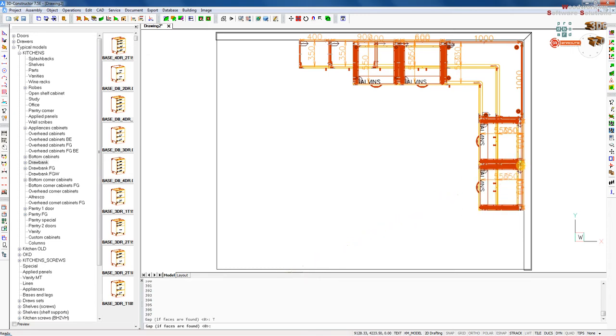because as soon as we drag and drop all the cabinets, we've got a project and we can change everything in this project. So basically apply our materials, change hardware, change sizes of the reveals, change the toe kick, and so on and so on. We can change general parameters, which are sitting in the user created standards in the global variable section. In particular, this way, I do prefer to finish off the design.